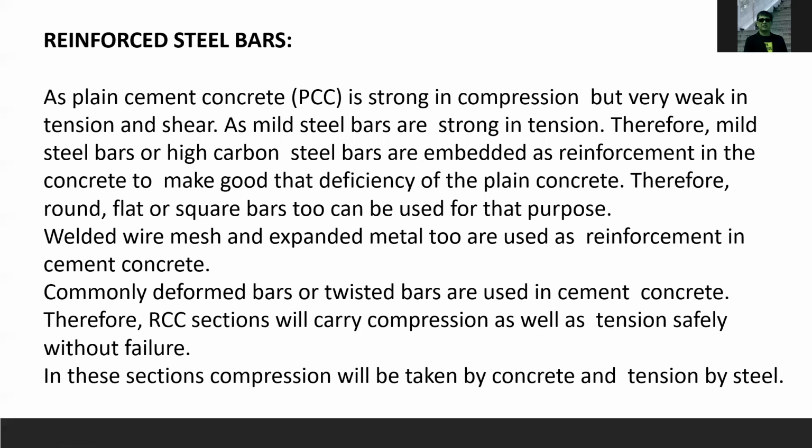Therefore, reinforced concrete sections will carry compression as well as tension safely without failure. In this section, compression will be taken by the concrete and tension will be taken by the steel. So basically, the main purpose of the steel in a reinforced concrete structure is for the tension.